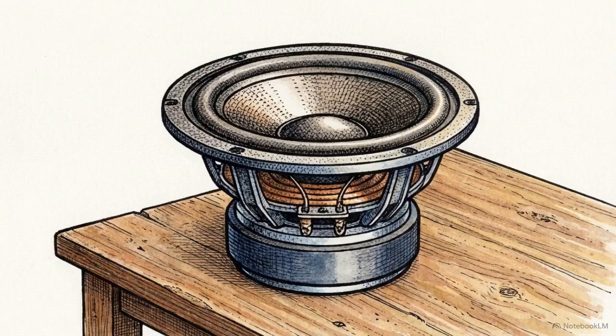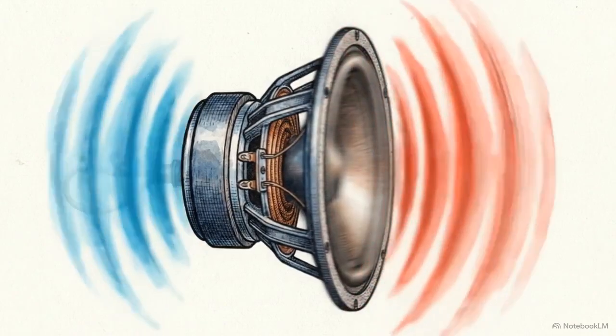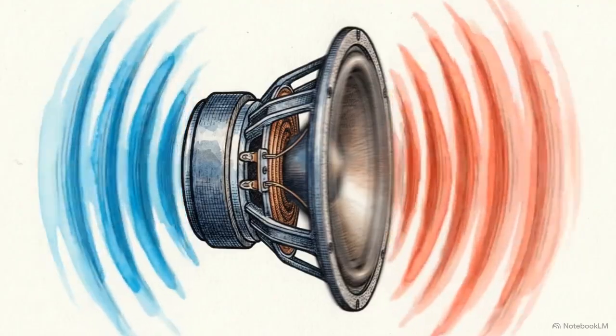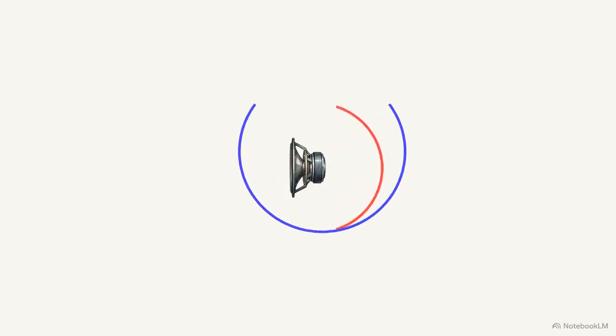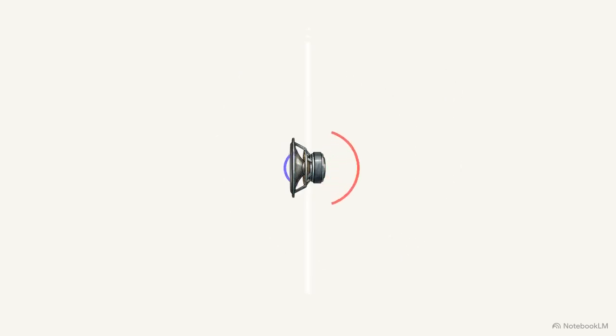Even with specialized drivers, a bare speaker moving in open air will fail to produce bass. As the cone pushes forward to create a positive pressure wave, it simultaneously creates a negative pressure wave directly behind it. Because low-frequency waves are long and diffuse, the rear sound wave simply wraps around the edge of the driver and neutralizes the front sound wave. This front-to-back cancellation destroys the bass reproduction entirely.